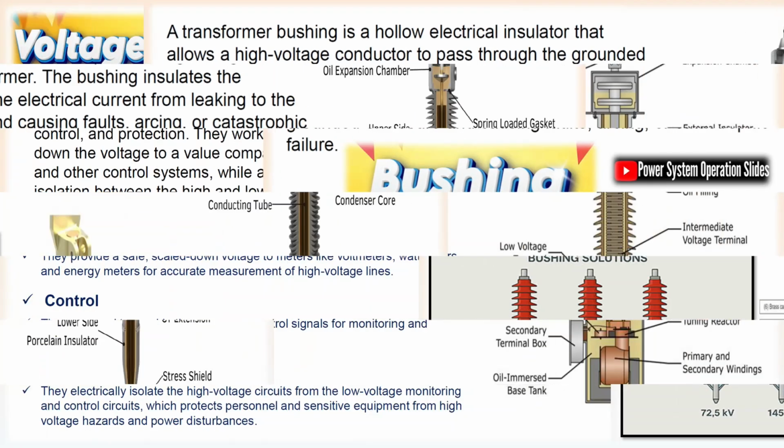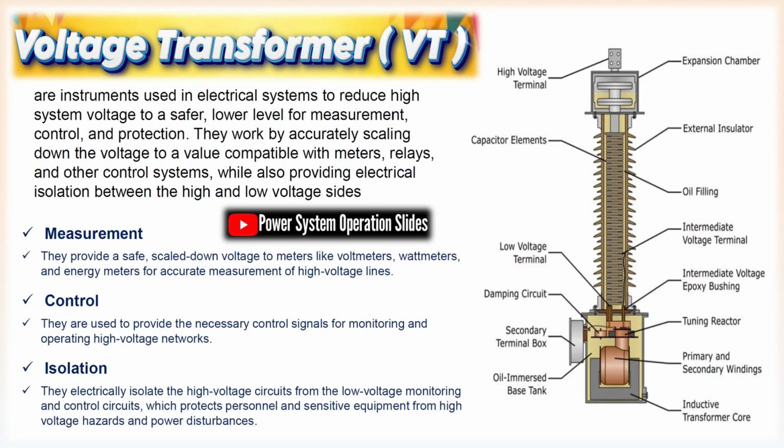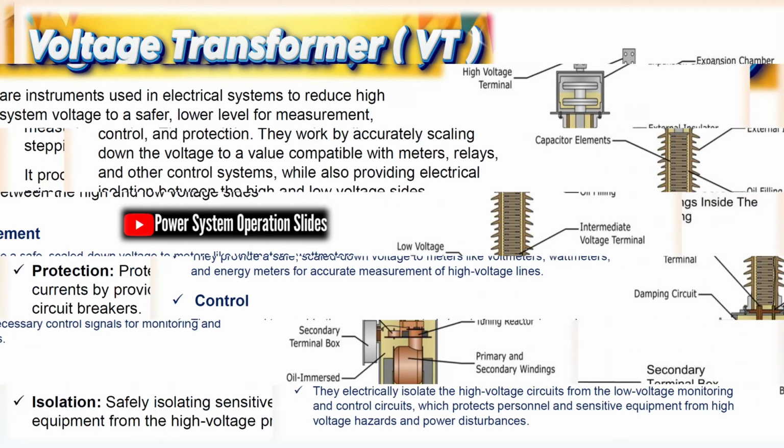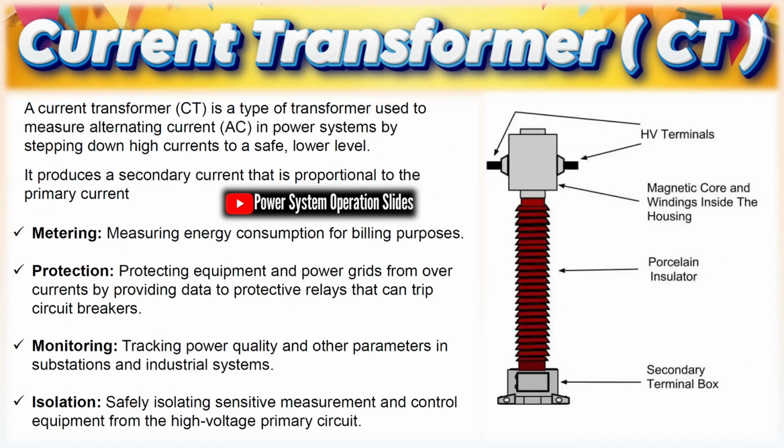Oil level indicators, OLI and MOI. OLI devices show transformer oil level, while MOI uses magnetic coupling for leak-free indication. MOI often includes alarm switches for abnormal levels. Both ensure proper insulation and cooling performance.